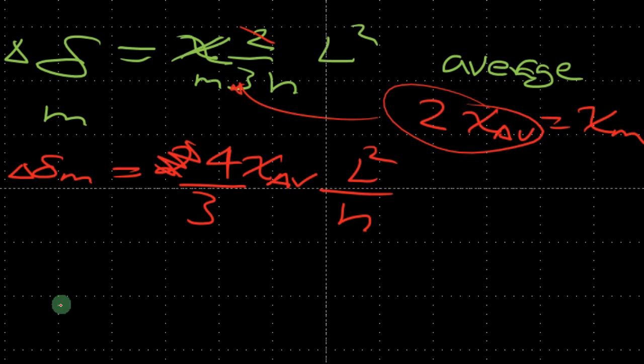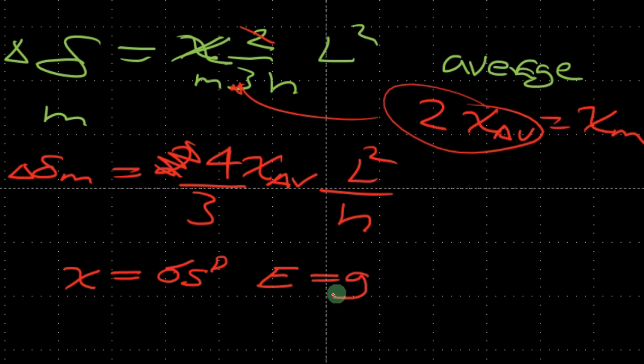So if you want to apply a force to an open circuit piezo, the strain is going to be according to the elastic compliance under constant electric displacement. So if we want to draw the stress, it's going to be like that. And the electric field generated is going to equal G times the stress.